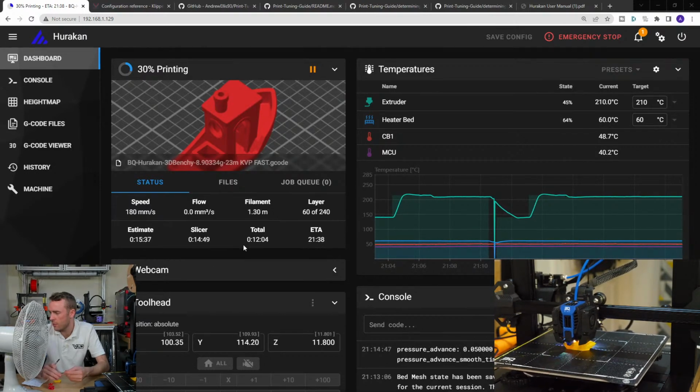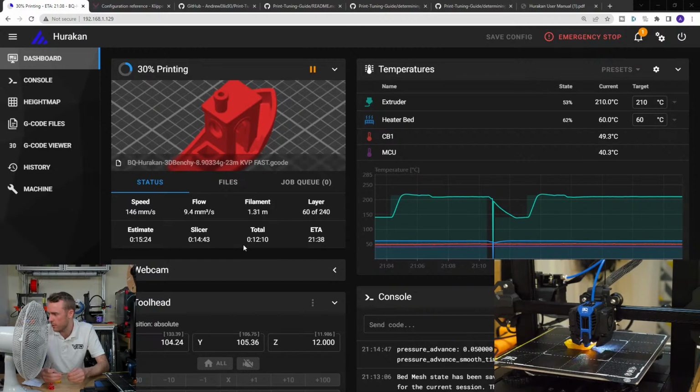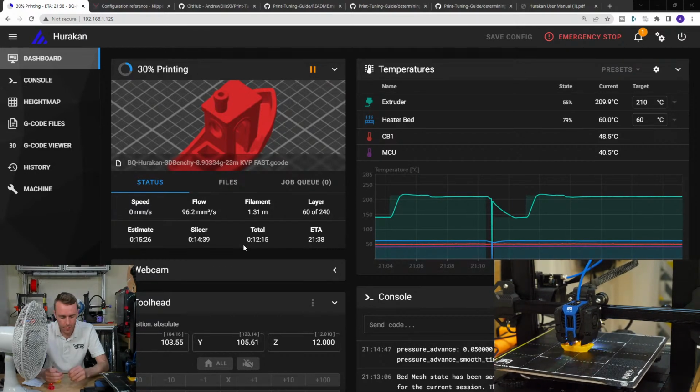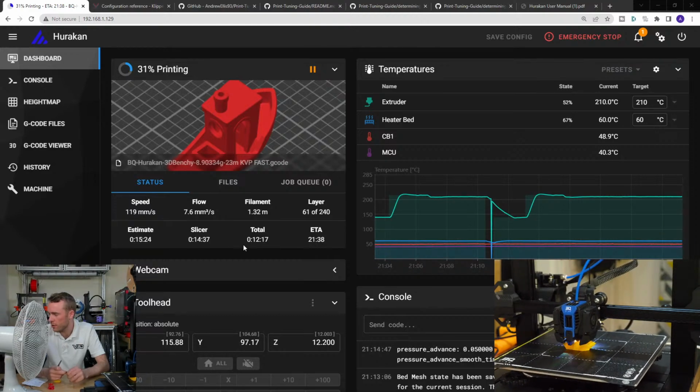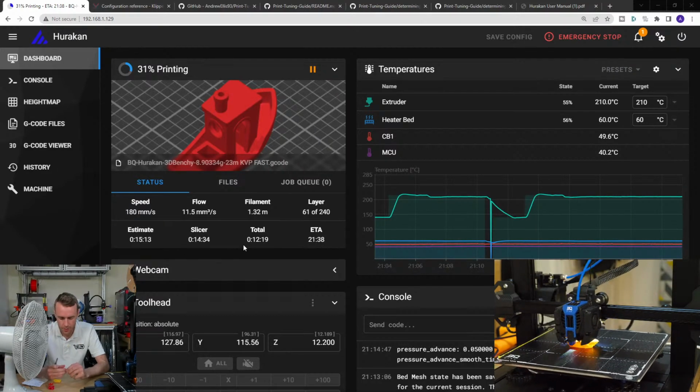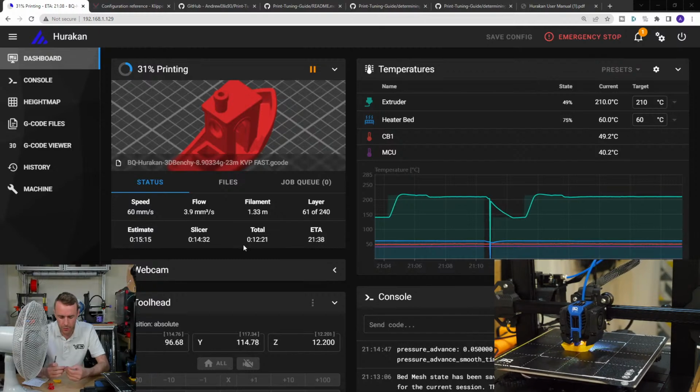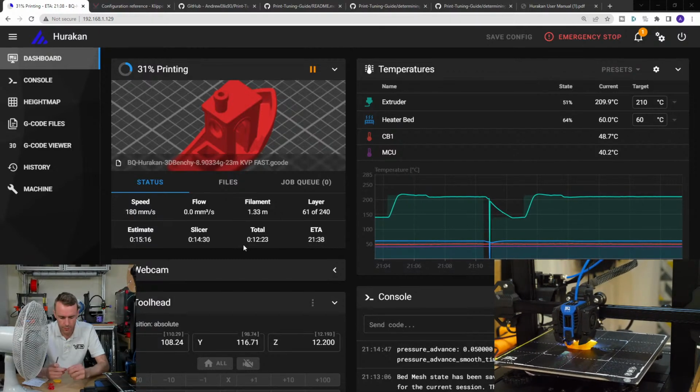No, PLA should get higher flow rates than ABS. But it's no good for printing fast things tiny, because you have to cool it. The extrusion force that I tested suggested that for equivalent flow rates, PLA requires less force.